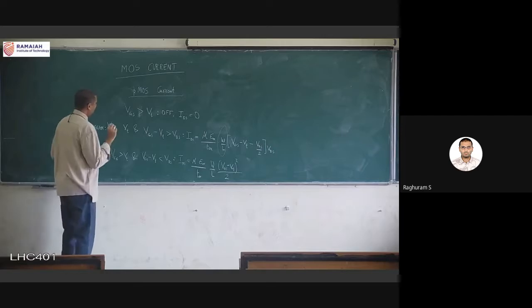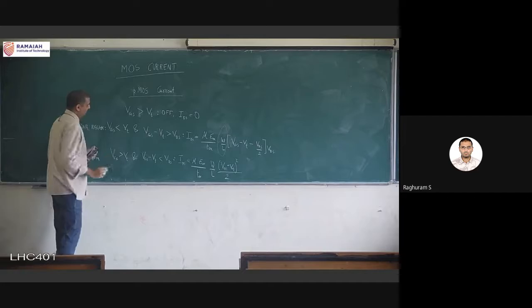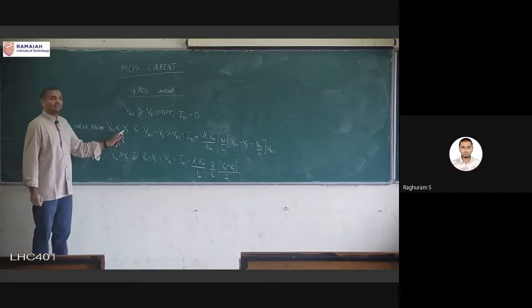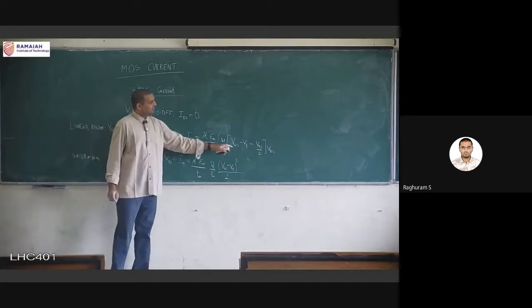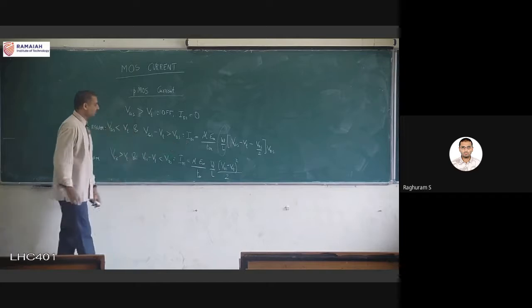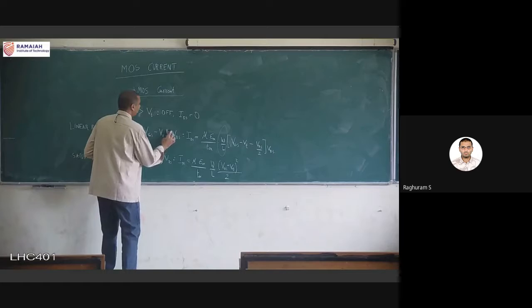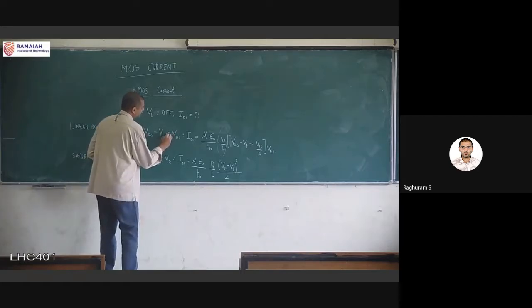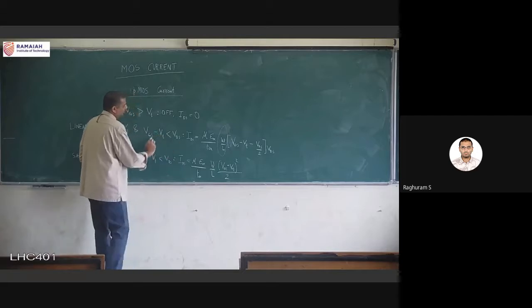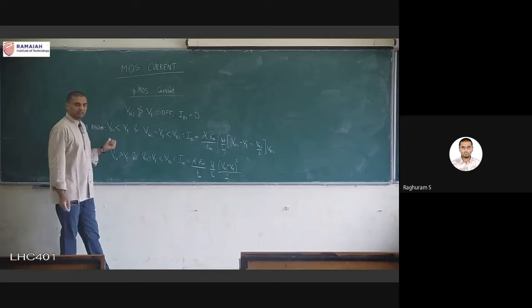Okay, first it has to be on. What is the condition for on? VGS lesser than VT. Okay, and now we will look at this, which is still called the linear region. So for the linear region, this condition also has to be reversed. If this condition is true, then the PMOS transistor is considered to be in the linear region.